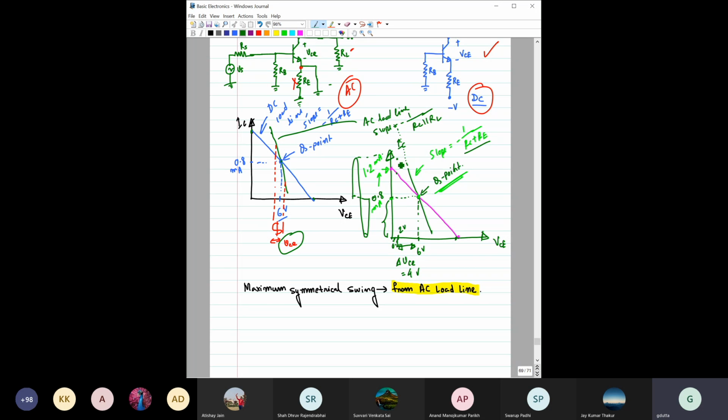It should be here. So you can make a swing up to 0.2, but the transistor is still in the active region only. However, this total current is here. See, it is 0.8, another swing is 0.8, so it is 1.6 milliamps. And this current is obviously higher than the maximum DC current. Is this point clear to you?